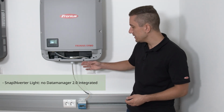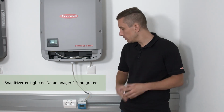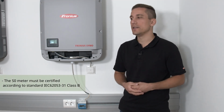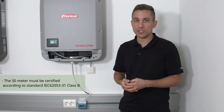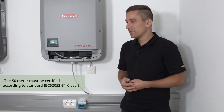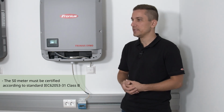So in our case, you can easily connect the S0 meter directly to the inverter and therefore do the dynamic power reduction with the inverter itself. Please note, you need, of course, on one hand the S0 meter. This S0 meter must be certified after IEC 62053-31. So please take care when reading the datasheet of the S0 meter that the IEC norm is covered, so that the smart meter can communicate with the inverter. Furthermore, we need to have Class B certification with the S0 meter, so please take care that these two regulations are met by the S0 meter.